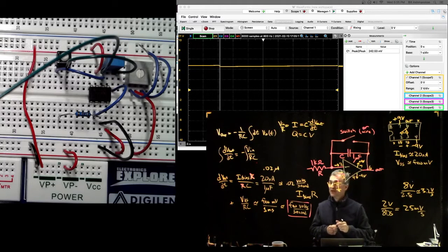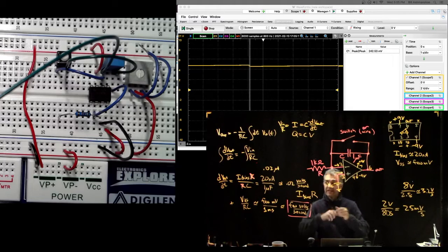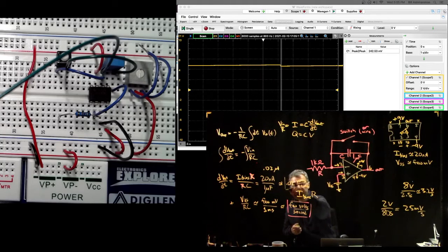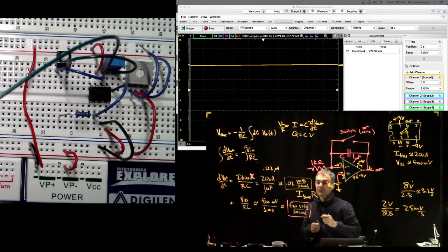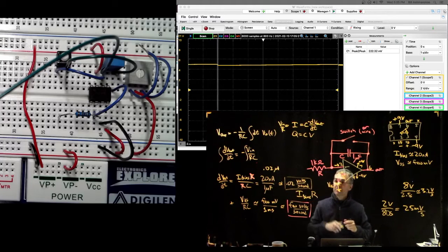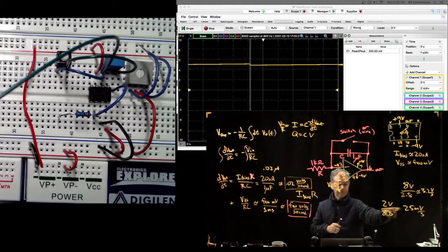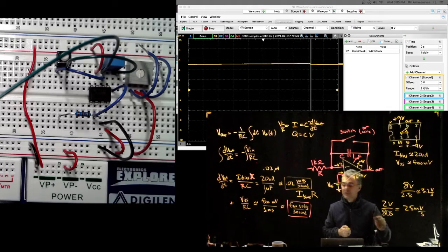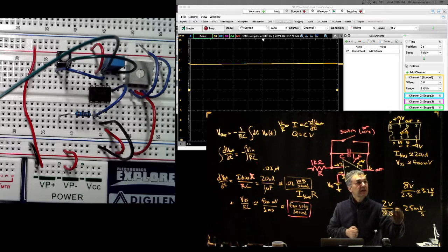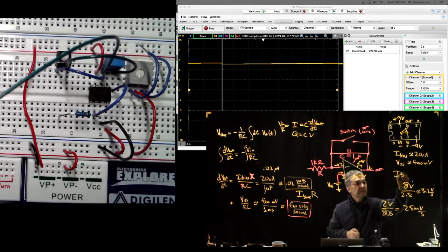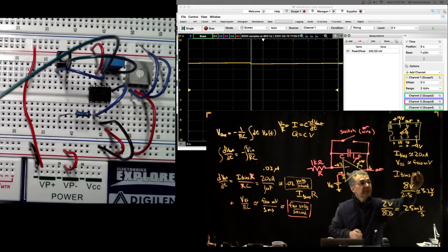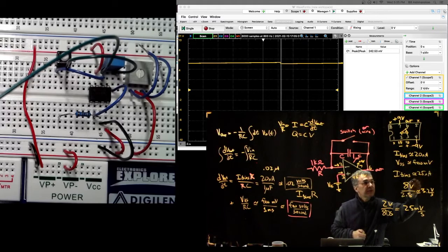And then we can say, oh, hey, that's pretty interesting. Because if it were 20 nanoamps, that would give us 20 millivolts per second. So actually, I guess what we're saying is that this corresponds to Ibias about 25 nanoamps. Okay, so cool.